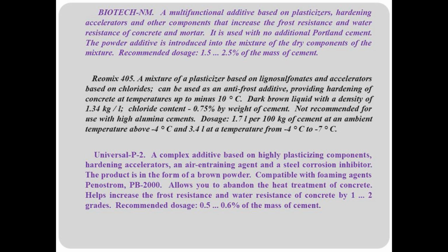The powder additive is introduced into the mixture of the dry components of the mixture. Recommended dosage 1.5 to 2.5% of the mass of cement.